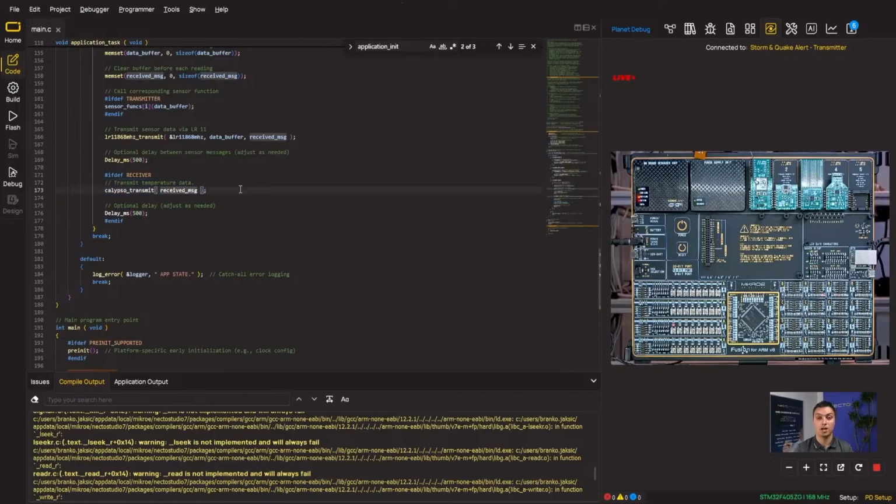I'm going to use Wi-Fi capability to transmit data that I just received, and send it to, for example, a Docker-based TCP server, which I'm going to demo for about 15 minutes. Each loop is delayed with 500 milliseconds to manage timing between packets.